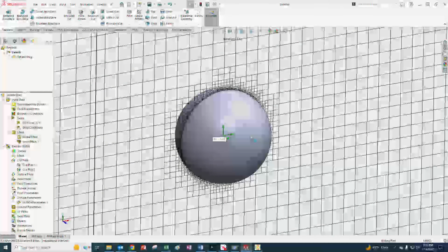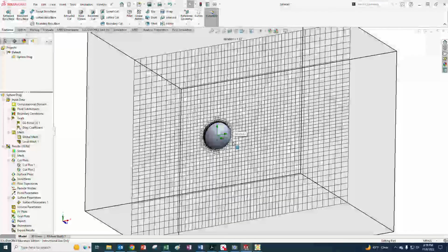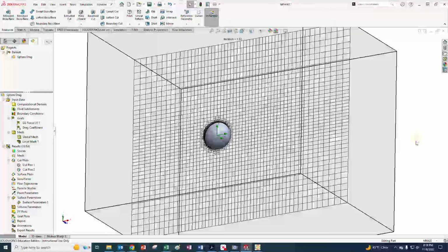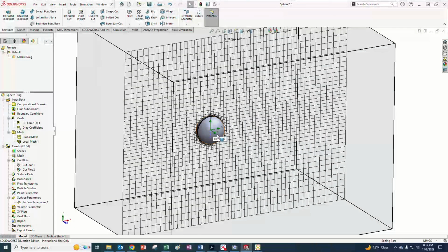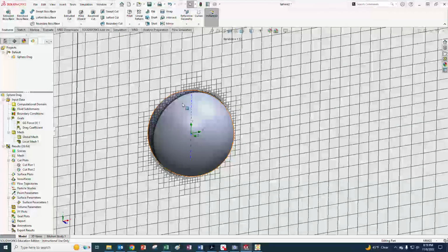But you might want to find out something that's three-dimensional. So I'm not discouraging you from doing it. I'm just giving you a warning that when you go to do a three-dimensional plot, you have the potential to really slow it down by making your grid too fine. But it is important to check and see what the effect of the grid mesh is. So this might have been too much of a grid refinement. We could try something a little bit less and make a couple different grid changes and see what happens.